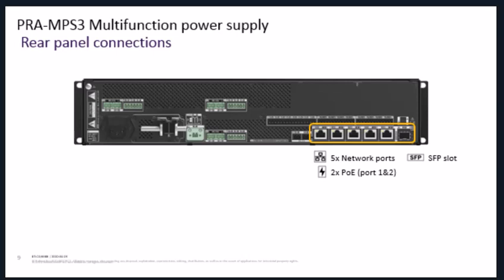Here in this device, yes, it's a switch like we show with the yellow mark here. But it's also a power supply for 3 amplifiers. You see here, this is for the first amplifier, second amplifier, and third amplifier. Powers up 3 amplifiers. That's the reason why we call it MPS3 actually. And then it's also a power supply for system controller. So it sends a 24-volt dual connection to system controller. And as you see here, it's also a battery charger.